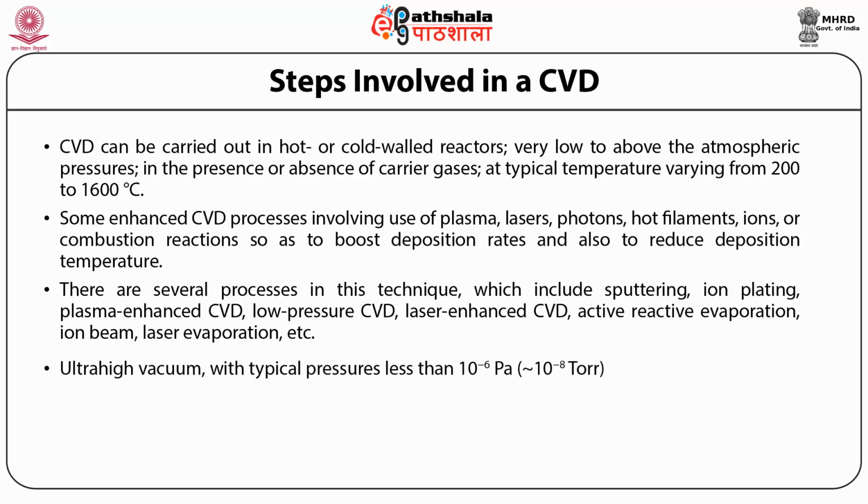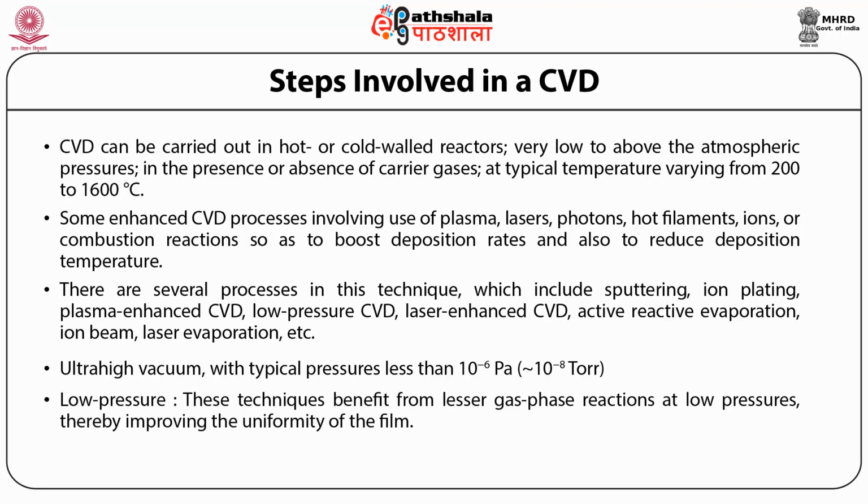First, ultra-high vacuum, which corresponds to pressures less than 10 to the power minus 6 Pascal, or approximately 10 to the power minus 8 torr. Then the low pressure: these techniques benefit from lesser gas phase reactions at low pressures, thereby improving the uniformity of the film. Last one is the atmospheric pressure.